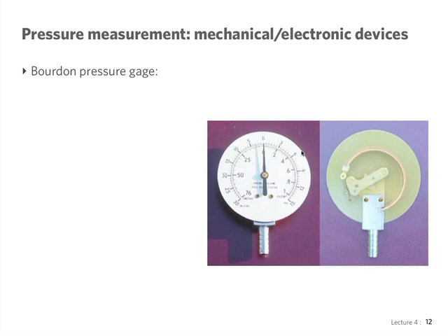But if we have a complicated system with very high pressures, or pressures that change in time and we want to record that, we need an electronic device of some sort. So there are some modern devices that we can use for those applications. This one is a Bourdon pressure gauge, which uses a mechanical element. The mechanical element is shown in this picture over here. It's really a hollow, curved tube of metal.